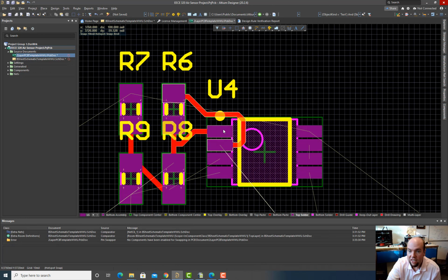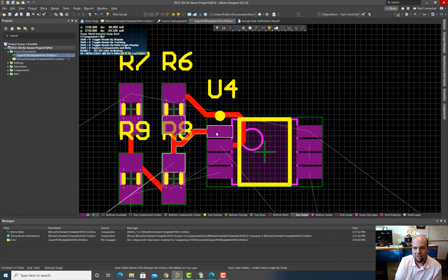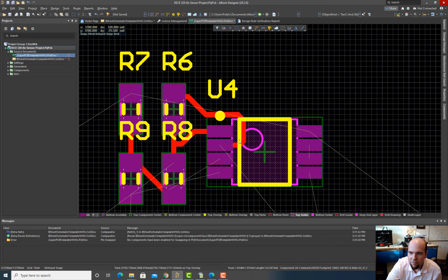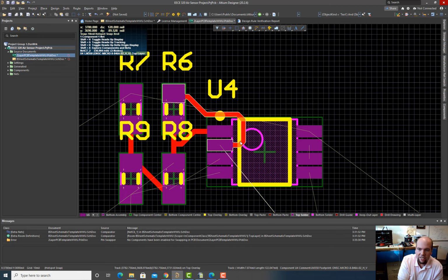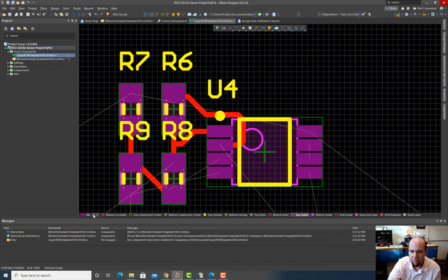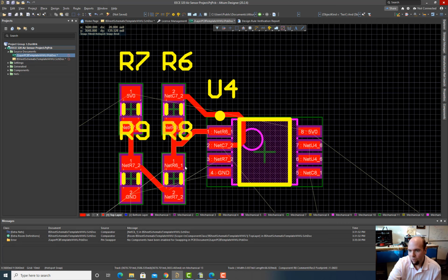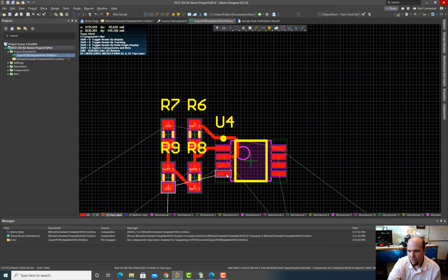And the problem is, if the fab, when it's printing these boards, has this layer a little bit misaligned, it's possible that if you run the metal too close to this other metal, it's going to expose just a little sliver of that metal. And then it's possible to get solder bridges. So if I'm routing metal around these openings in the solder mask, I like to give them space. Unless I have to keep them tight, I'll give them a lot of space. I probably am going overkill with it, but if I don't have to keep it all nice and compact, why not give it some breathing room here.